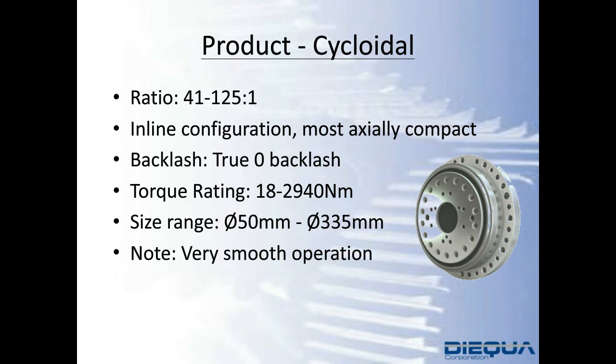In combination with the twin cycloidal drive system, the use of cross roller bearings on the output flanges lend themselves to much higher mechanical capacity in a smaller size. Generally, if we compare size to size, it will be 2 to 2.5 times or higher in mechanical strength capability. Roberto, thank you. Excellent, thank you.